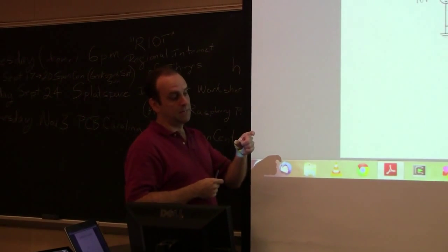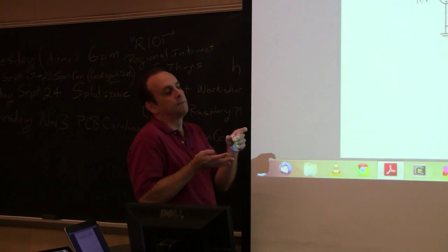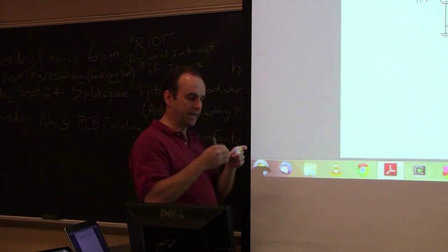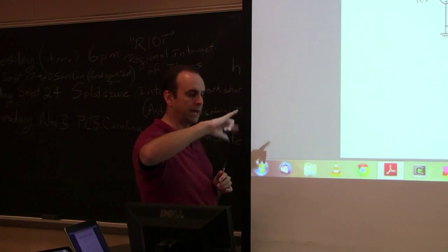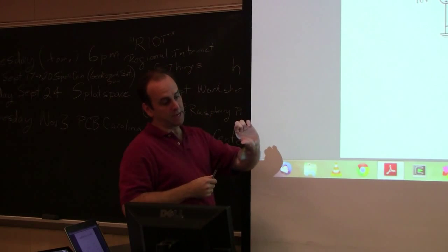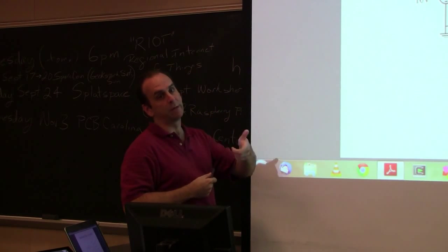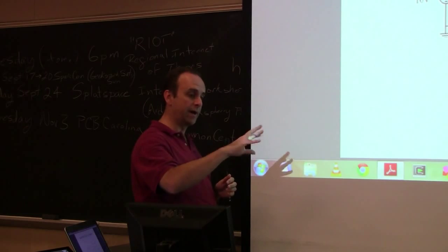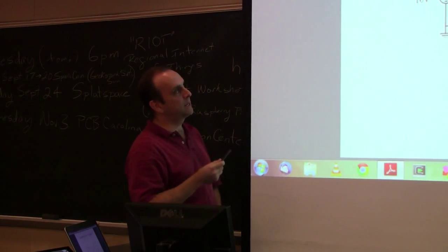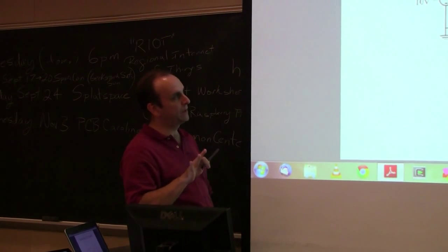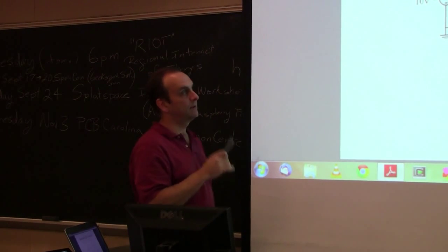Even the most expensive dielectrics have charged particles. They have dipoles embedded in the dielectric. So when the voltage is changing outside the capacitor, these little dipoles inside the dielectric are moving, so that results in loss. Anytime you move matter, you have to exert energy. So there is no such thing as a real capacitor that is only capacitive. But for this purpose, it exists today.